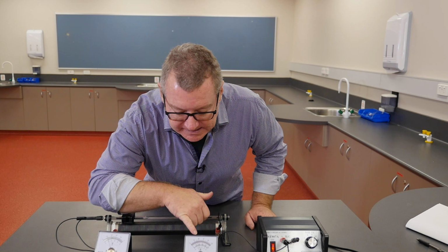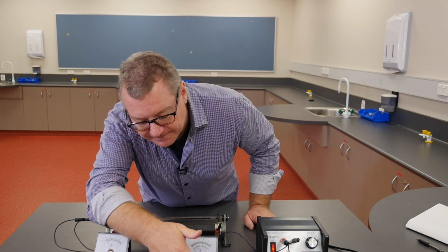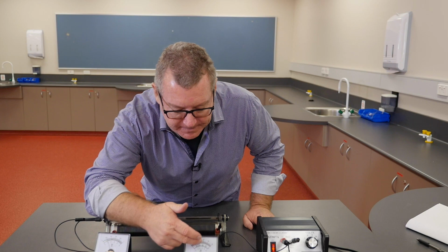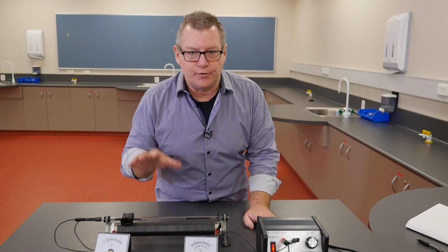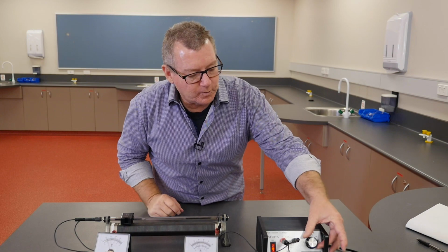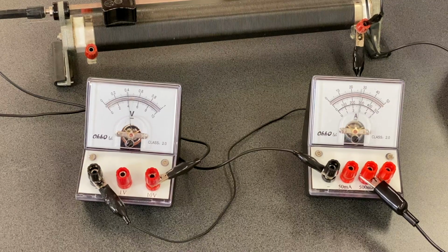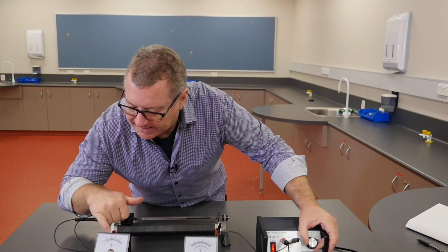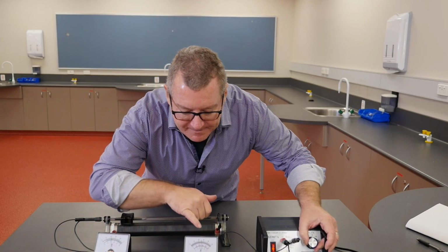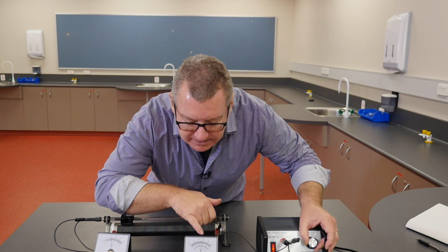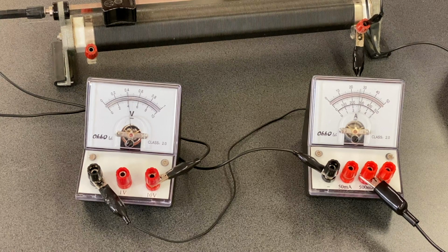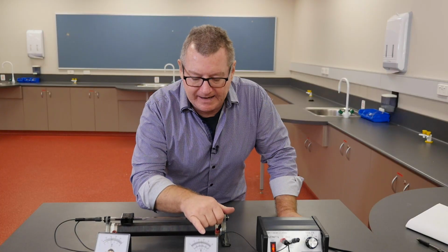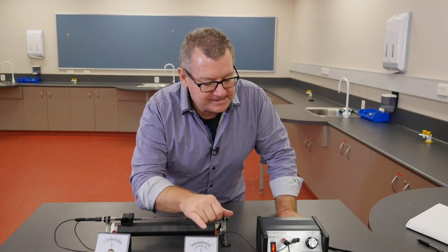And for our current, the scale that we're on is the 500 milliamp scale, so it's that middle scale. It's about 150 milliamps that we're actually measuring as a current. So at 2 volts input, that's the current that we get through this particular resistor. We can go up to 4 volts input. At 4 volts, we read, again, very slightly over 4 volts on the voltmeter. And on the ammeter, we read about 250 milliamps, 260 maybe. So we can measure that precisely with the meter, and we've got our second reading.